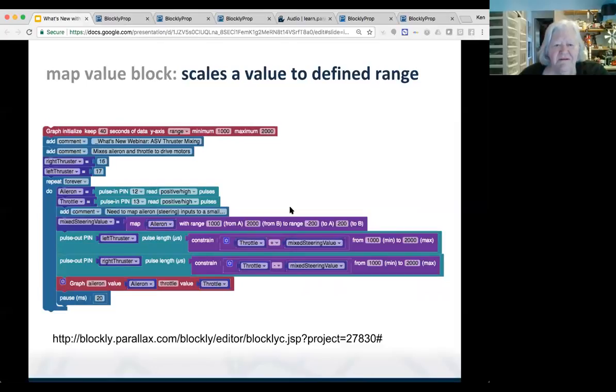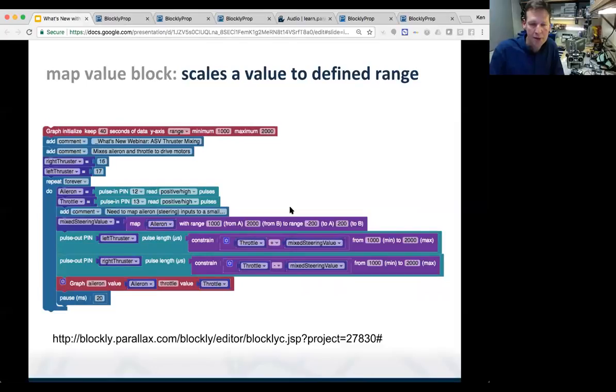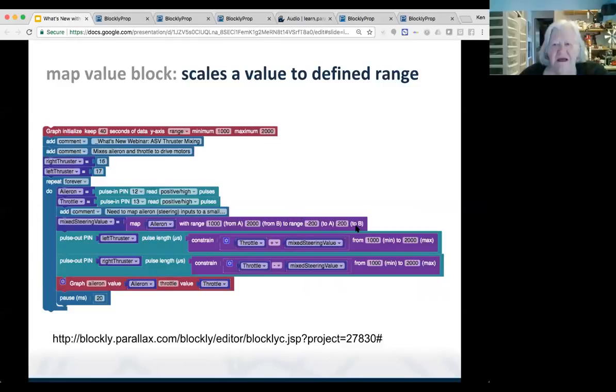Yeah, some of this programming could be done on the radios or it could be done in the microcontrollers. So on this boat, there's a propeller activity board which sits between the receiver and the ESCs. I made mine so that I could switch it using the radio and the gear, what they call the gear switch up on the radio. I can switch the radio back and forth between RC or autonomous.